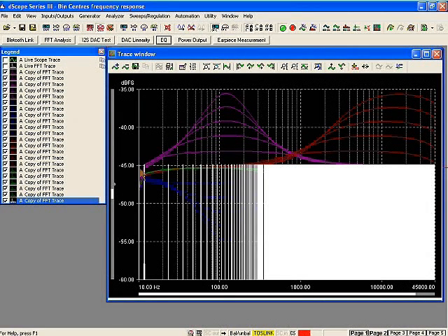This is the white trace that you see highlighted currently, and you can see these individual tone components that are the constituent parts of the multitone, the bin centers multitone that I just introduced you to. And once again, if I turn up the monitor volume control on my Dscope hardware, we can actually have a listen to that. Hopefully you heard that. It's a broadband stimulus that sounds very much like noise, and the more tones we have in there, the more noise-like the signal starts to appear.